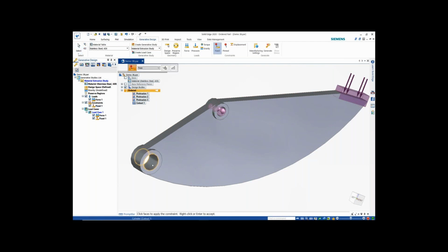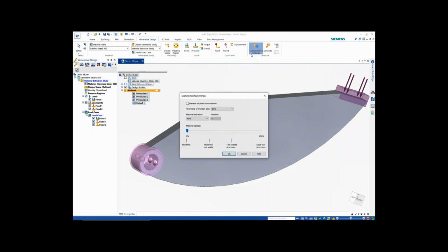So these two areas on the model would be considered constrained by some other geometry, and you can give it a diameter. Obviously, you see in the inputs. And then a couple of settings here are important. The direction that we want the extrude to happen in. Maybe I'll go and turn on the coordinate system.